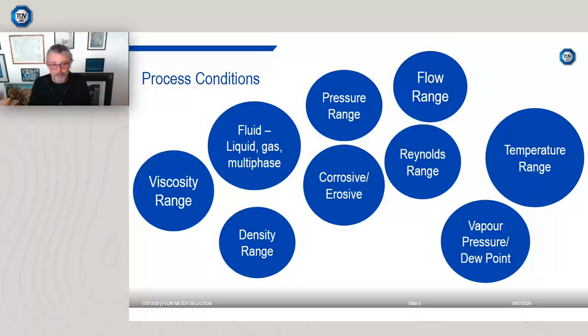And finally, on this slide, is the nature of the fluid. Is the fluid benign like water, in which case there are not many meters that can't cope with measuring water or air, for example? Or is it really corrosive and erosive? Is it a gas, for example, that has a high hydrogen sulfide content? There are certain meters that you just do not want to expose to that type of fluid, because they won't last very long, they'll break down.